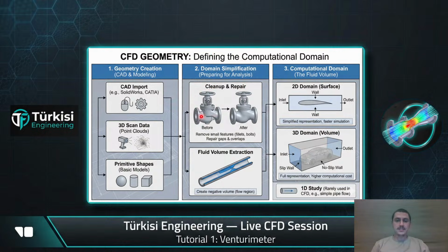So you take this geometry, repair it, and maybe even simplify it more. You remove the bolts, screws, sharp edges, and unnecessary chamfers or fillets, or you add some chamfers and fillets sometimes. You simplify your geometry as much as possible to reduce the load on the computer. You want to solve the problem, and there are some unnecessary details in the CAD file.